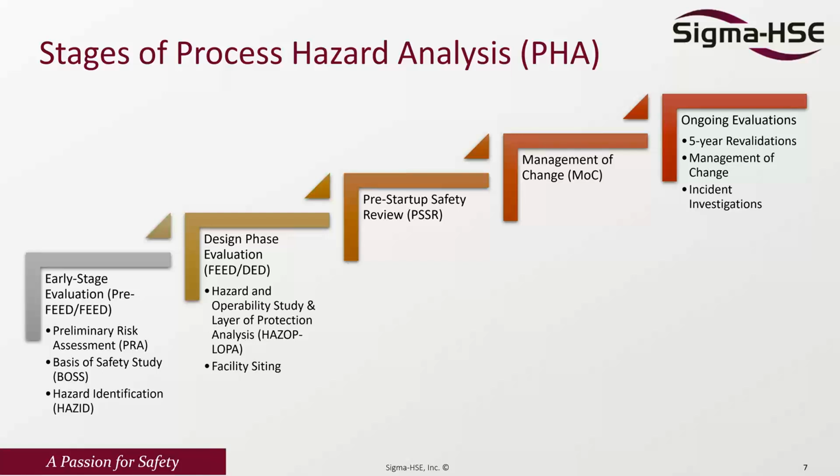After the construction of the project is nearing completion, we will do a pre-startup safety review to ensure that all of the recommendations in the previous 2 stages have been completed and are in place. Any changes during the pre-startup safety review should be handled under a management of change.